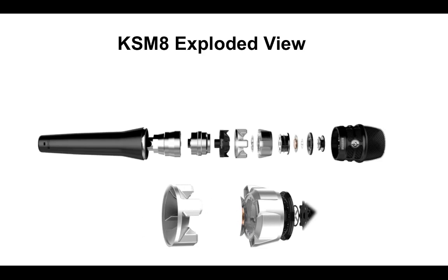We had to develop an entirely new welding process, so we actually laser weld these two cartridge parts together from the inside out. And there's these little prongs that come in and weld each of these tube systems. These are filled with air, and that's how the airflow routes around the microphone.